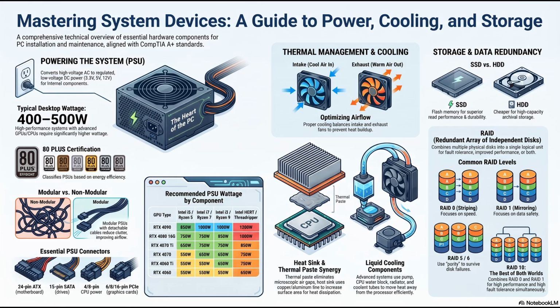A well-designed computer case operates fundamentally as a wind tunnel. You establish this by carefully orienting case fans. You mount intake fans at the front and bottom of the case. Their sole job is to ingest cool, ambient air from the room. And then you balance them with exhaust fans. Positioned at the rear and the very top of the case, leaning into the physical reality that hot air naturally rises. The exhaust fans capture the heat radiating off the internal components and forcefully blast it out the back. You're orchestrating a continuous flowing river of air. Cool in the front, hot out the back.